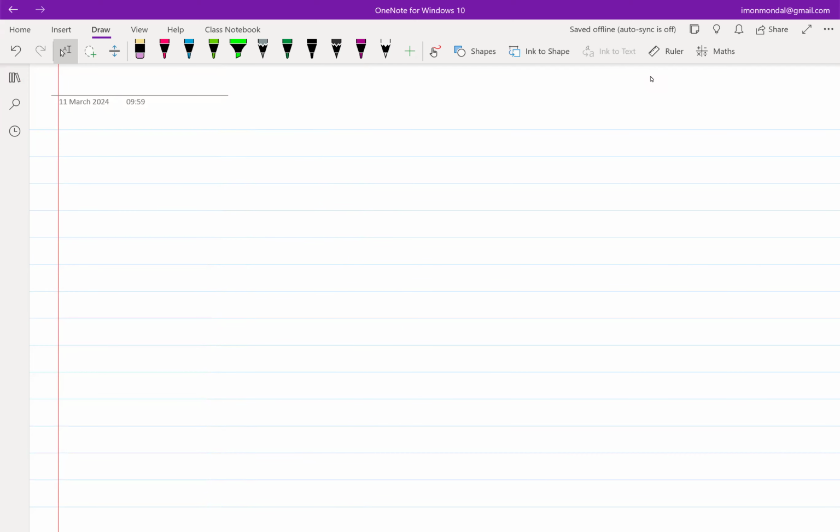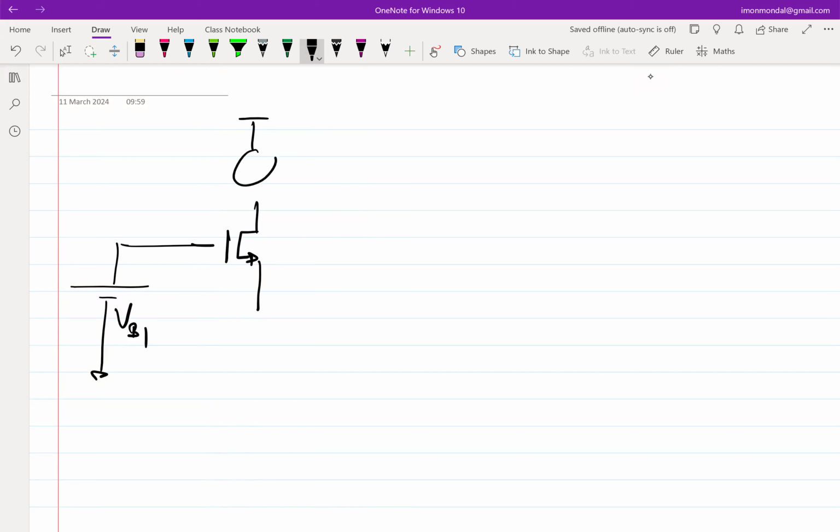So by definition, what are we trying to do? We are saying that we have this transistor, and we will not touch the gate. So the gate will be some bias voltage. What the requirement or the value of this bias voltage will be, we'll figure out later. But as of now, the current source will be applied to the drain, right? And we'll have to do something to the source. So this is the third in the list. That is, we apply the current source at the drain, that is, observe the drain voltage and tweak the source voltage.